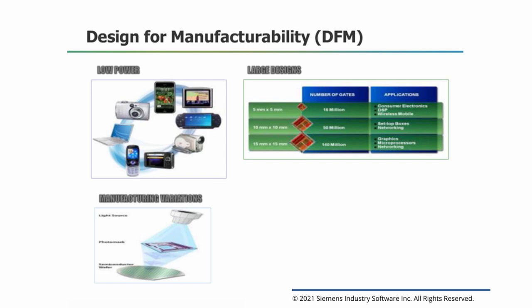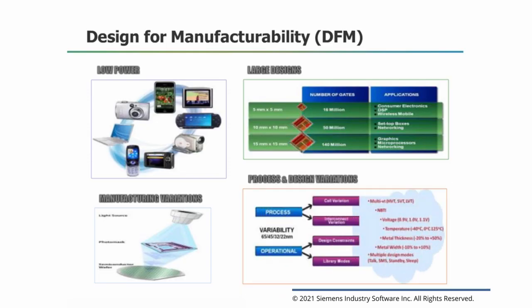Complexity of the system and the verification of design errors is one aspect. Sub-wavelength lithography leads to large spreads in timing and power for digital circuits and in performance for analog circuits. The extreme process variations, which affect transistor geometry and spatial variation in threshold voltage, is just another aspect. So, can it be manufactured? What is the cost of manufacturing? And what is the yield? Are 3 very important questions.